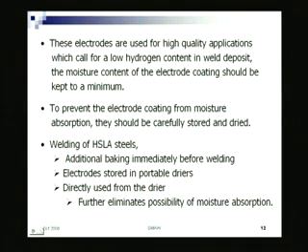It's something like, if you have seen the Ramayana and all that, Rama used to carry a container of arrows, something exactly similar. That kind of a thing. Instead of arrows, you keep the electrodes, okay, and that is electrically connected, such that you continuously keep them at an elevated temperature, and just take out the hot electrode and start welding, such that you minimize the possibility of moisture absorption, right.